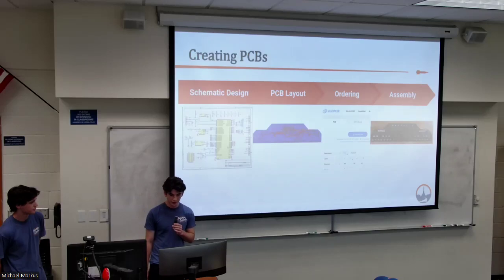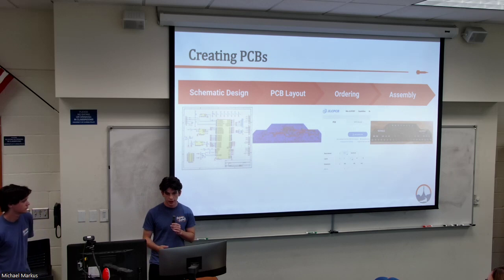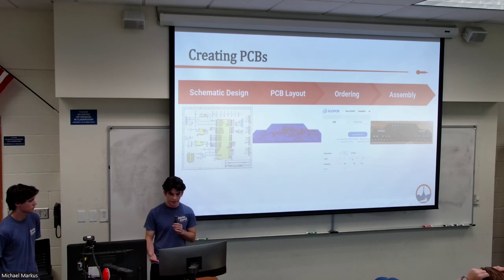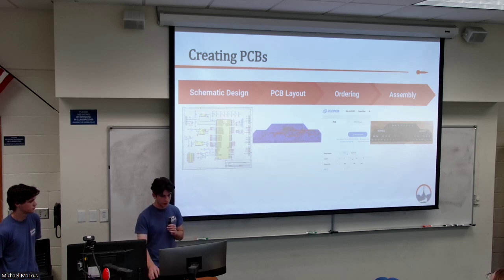So the process of creating a PCB is first you have your schematic, and a part not noted here is that oftentimes in a standard library, like when we go to do the demo later, the university has a standard parts library. Oftentimes the components that you need for your schematic won't be in that library. So you need to create the symbols for them yourself and create the footprints as they would appear on the PCB. The footprint is how much space it takes up on the PCB, basically, and where the pins are. So yeah, schematic design, PCB layout.